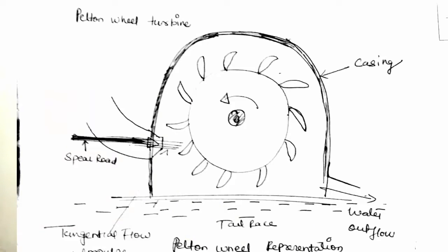So the next kind of turbine is a Kaplan turbine, which is used for low head up to 80 meters, and then there's a Francis turbine. This could be used from 80 to 100, 500, etc. And these are the impulse and reaction turbines.